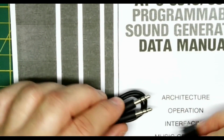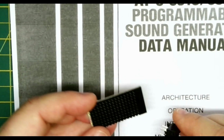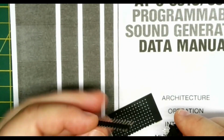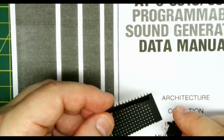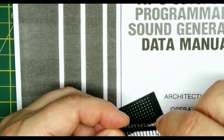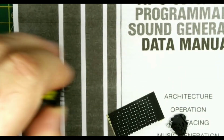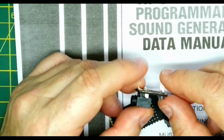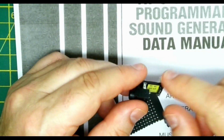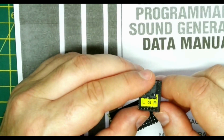So we need to create a little adapter for that, and what I've done is used a bit of stripboard. Just need to drill it out a little bit to make the holes a bit bigger. Then some 0.1 inch connectors. What I do with these is push the pins so that they go fully into the top of the plastic there, and then I put them in like this. So this is the connector that I've created. I solder the pins on this side and push them all the way through here, and you can see we've soldered all those in. It's fairly straightforward. So we've got the 5 pins there.